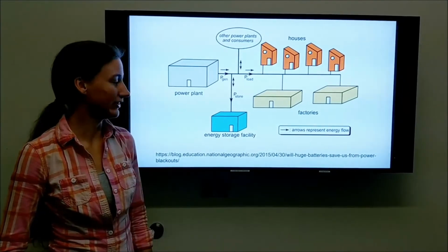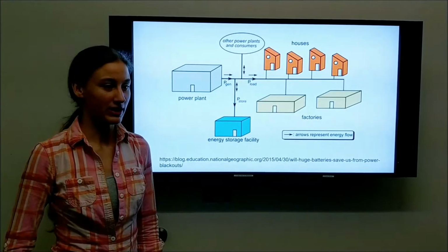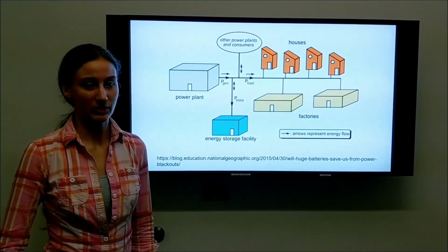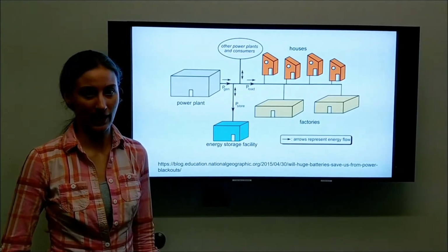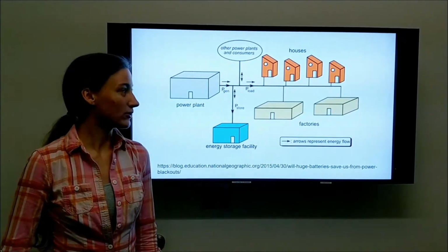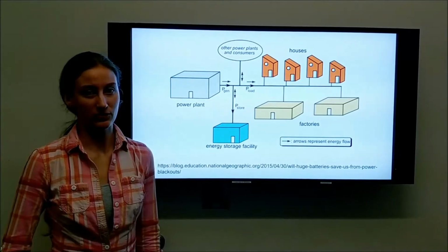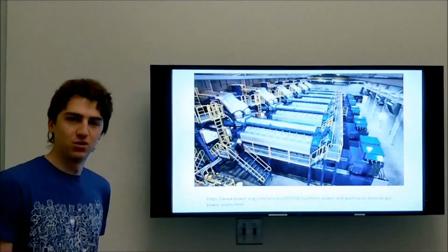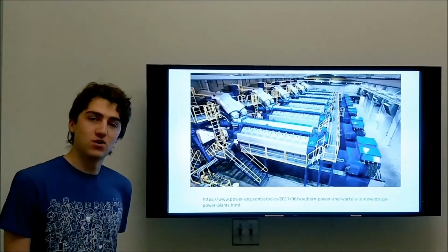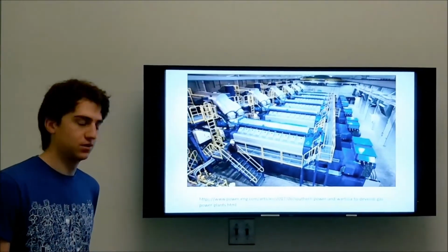Because we have so little energy storage, we need to make sure the feedback loop controls the power in to the turbines to equal the power out. Because we don't have a lot of storage, the energy generated needs to be used right away. Because the system is constantly changing in terms of the load required, the turbines always need to adjust the frequency to match 60 hertz. So the system in question that we chose to model was the turbine itself.